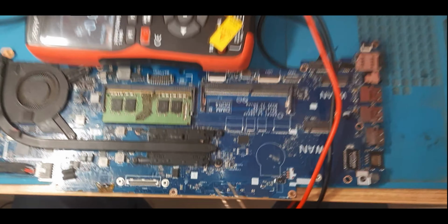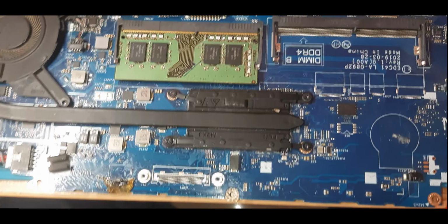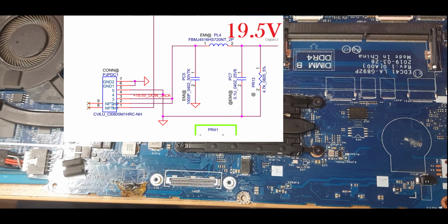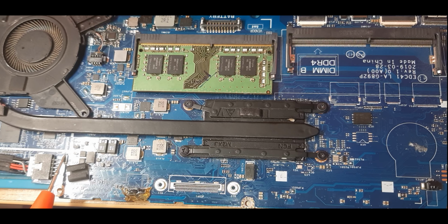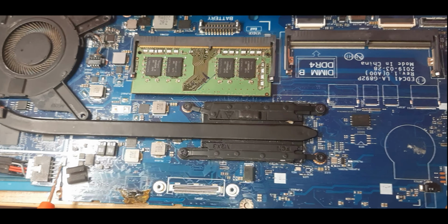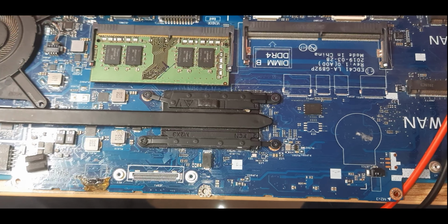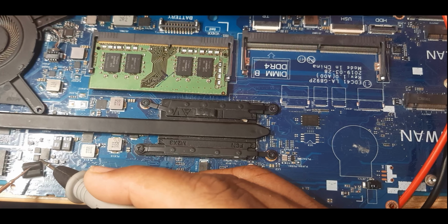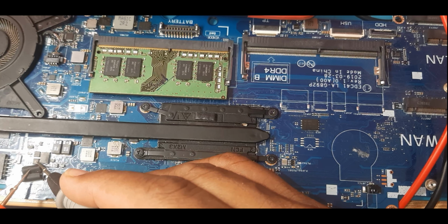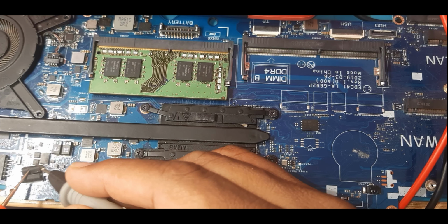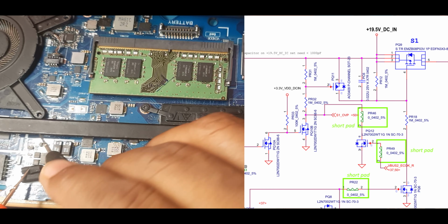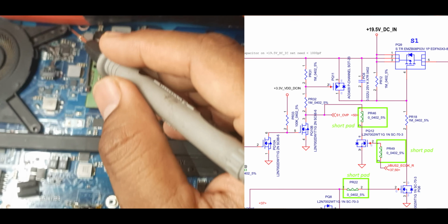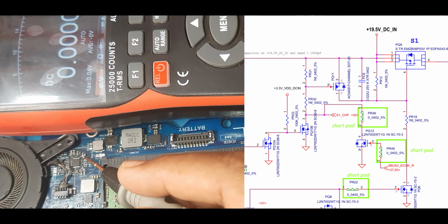Okay, see, the main thing is the supply. Here is a 19 volt supply. First it will come to this. First I will tell you how the logic will work, then I will give the supply and show you what exactly the voltage is. See, here PQ9 is the first MOSFET. After this, what voltage will come? That voltage goes to this particular charging IC as its input.